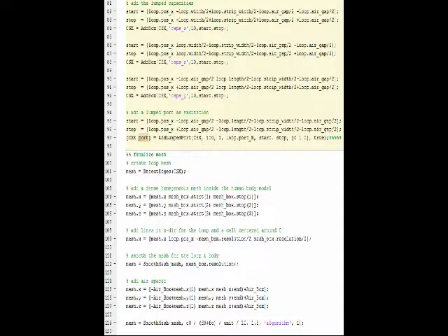After this, we create a lumped port as excitation points, taking loop parameters such as the air gap, position x, and strip width. We finally create the excitation points. Using the lumped port function, we excite this signal in the y direction only, because it is 0, 1, 0. The x and z directions are all zeros. Therefore, this signal will only show up in the y direction. Set it true so that we can see the result, and save it back into the CSX port matrix.